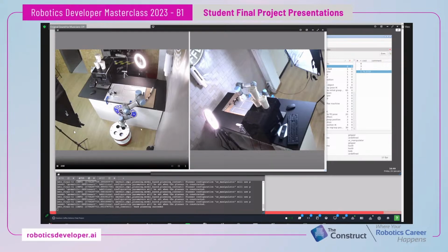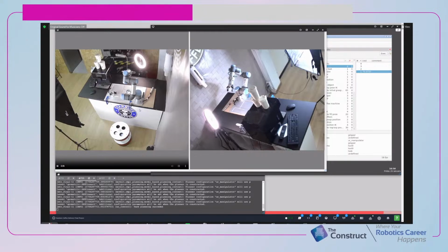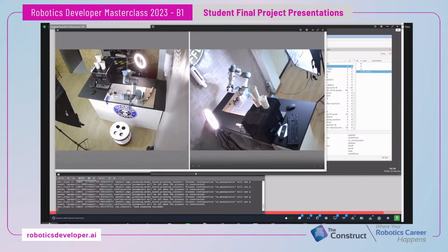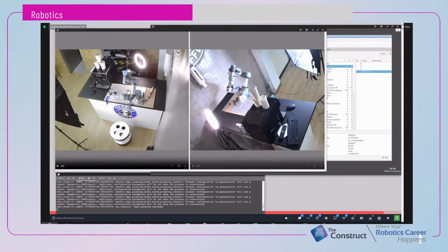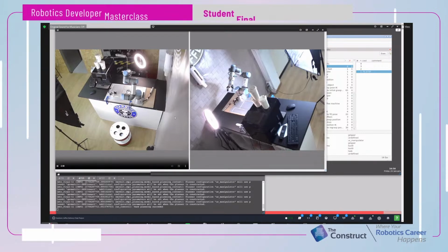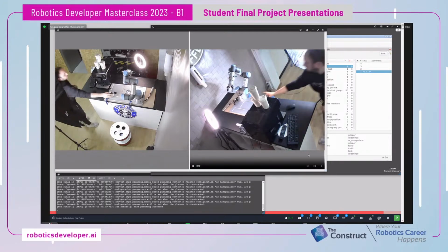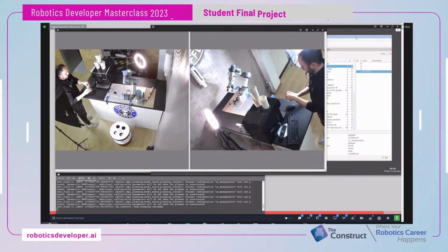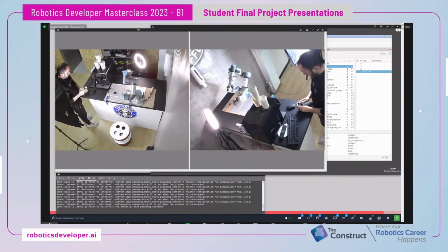So that is one of the things discussed: when the cup moves around, it springs back into position. It sometimes goes out of position from where the cup is expected to be, and then the gripper doesn't know where it actually is. So that in part would be solved by the minor workaround we have of trying to reinforce the cup, but then the gripper stopping with less pressure.